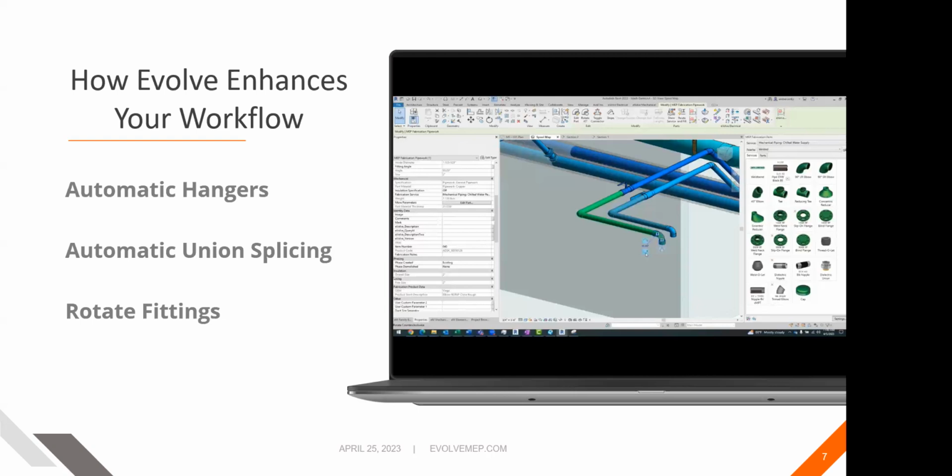I've got a bunch of questions coming in. Would you build a Revit schedule to get a BOM of fab parts, or use the CAD fabrication reports? I guess that depends on your workflow. I have done bill of material and fab parts within Revit. So if I'm designing and modeling within Revit with the fabrication parts, I would build my schedules out within Revit or bill of material, because I can still map those parameters out. Evolve will spool those too for you.